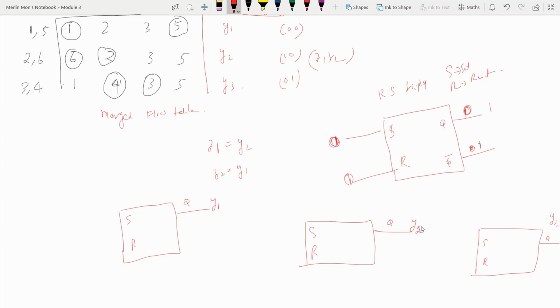So from looking at this, we can tell that if Y2 becomes 1, this will indicate the output Z1, and if Y3 becomes 1, it will indicate the output Z2. Because if Y2 becomes 1, only Z1 becomes 1, so we can represent Z1 by Y2. Similarly, only Z2 is 1 when Y3 becomes 1, so we represent Z2 using Y3, just like that.